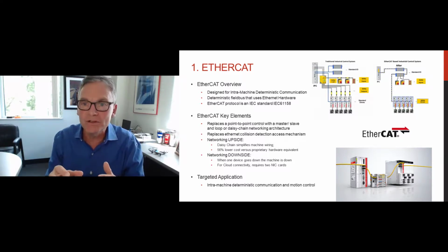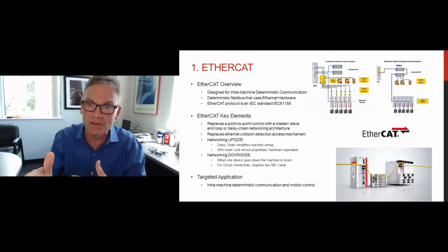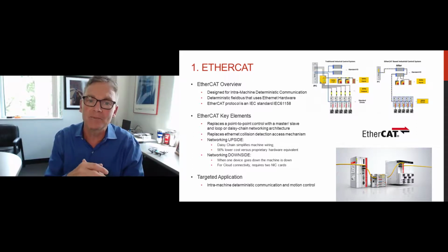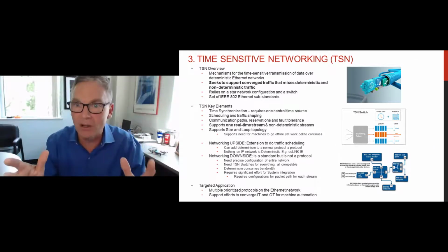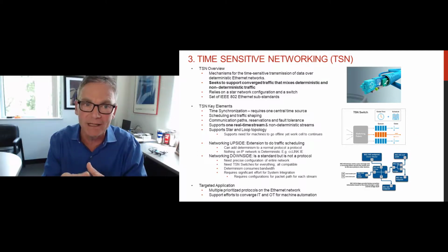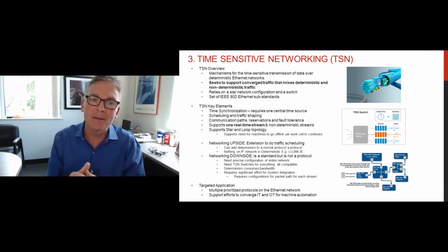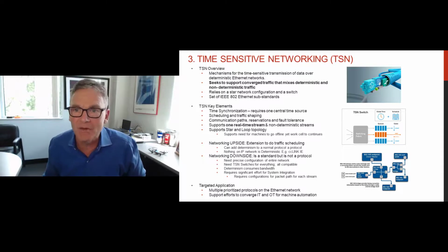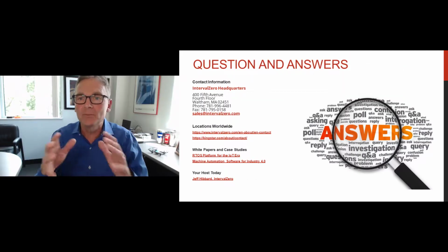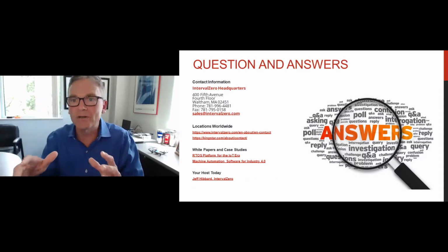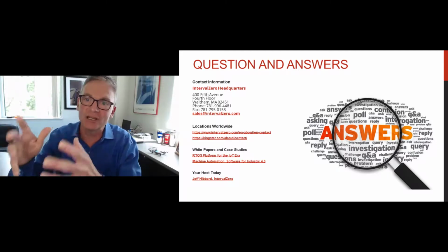So while there is some work to do, and you have to write your applications to handle the immediate stop and safety requirements, the architecture's all there, the hardware's all there. It's just a matter of making your applications ready. With respect to OPC UA, it's impossible to use OPC UA by itself for safety because it's not deterministic. In order to have safety, you have to have instant stop. So adding in TSN becomes a good solution. However, the integration then becomes a real problem because you have to create a whole other safety mechanism, which takes more integration and more switches and so on.